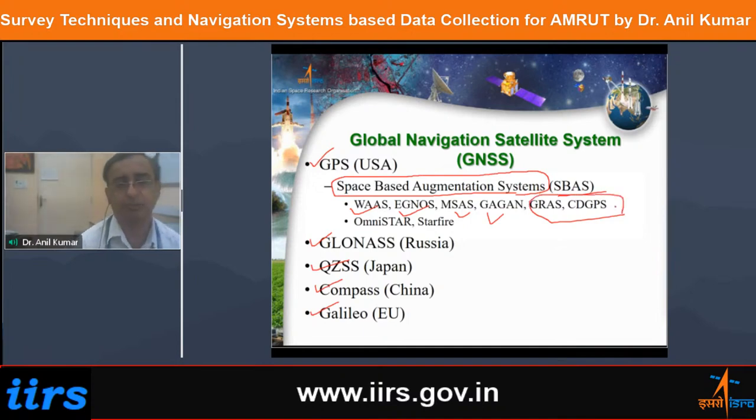What do they do? They apply satellite-based corrections to my GPS receiver, and the accuracy improves from 4 meter to 1 meter. Previously, there were OmniSTAR and StarFire. They established these corrections at the regional level.